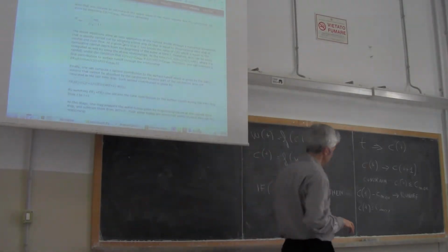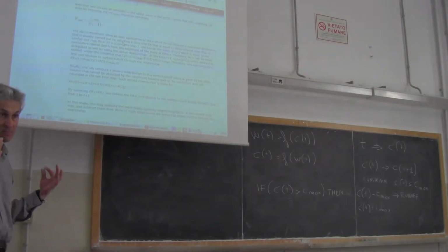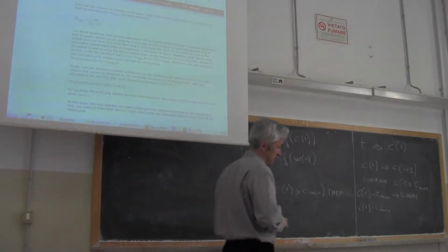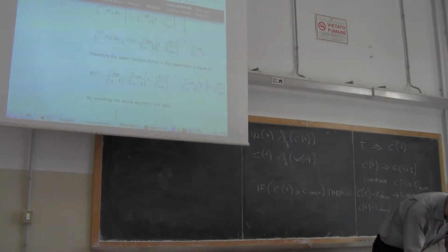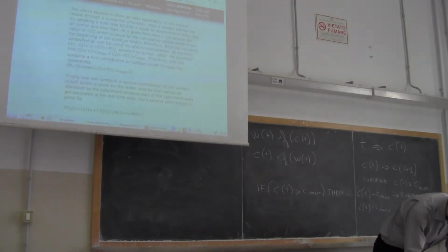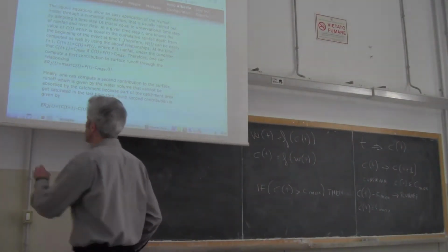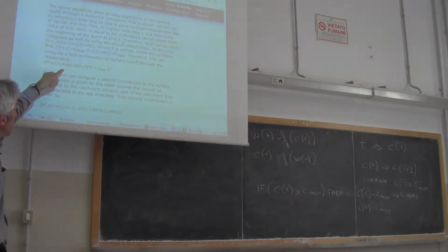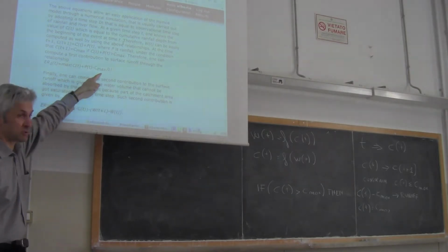In order to translate this condition into computer language, the best possible way is to compute a first contribution to surface runoff, called here ER1, which is equal to max of Ct plus Pt minus Cmax, and 0.